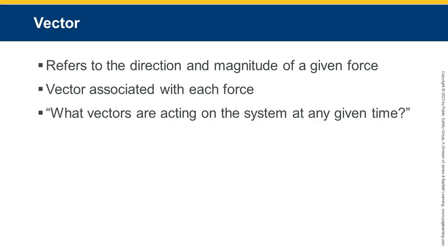So next time you rig, don't just look at the rope or the anchor. Look at the vectors in play. They'll tell you if your system is solid or if you need to make adjustments before something goes sideways.